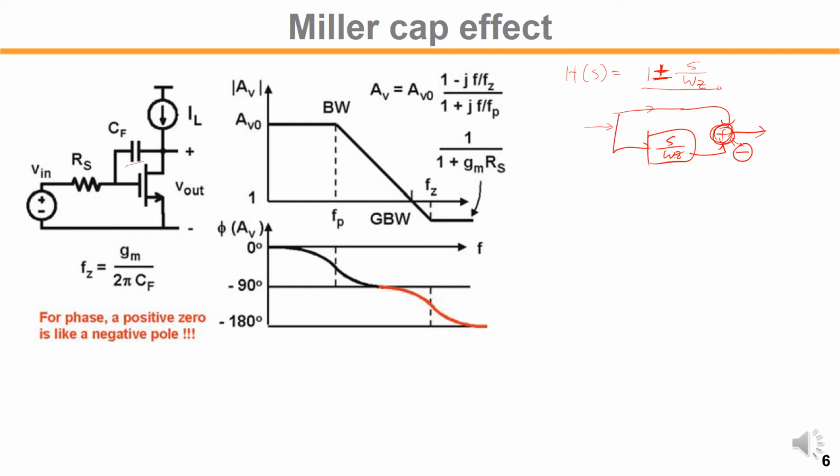So in this example, your signal comes in up until the input and then splits into one path and the other path here. At that point there are two separate paths, but one path has a frequency dependent component like a 1 over sCF. So you can find the zero frequency, a certain frequency where the output response becomes zero. So to find the zero frequency,